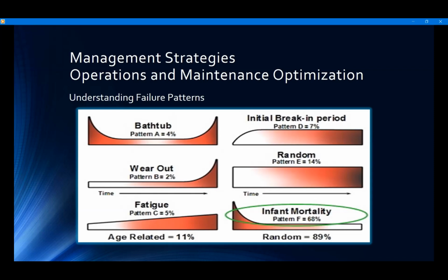Understanding these unique differences, an effective maintenance strategy can be developed. Age-related. These types of failures can be addressed through fixed-time maintenance. Fixed-time maintenance includes replacements, rehabs, overhauls, basic cleaning and lubrication. While cleaning and lubrication will not prevent wear out or corrosion, it can extend the life of the equipment. Random.